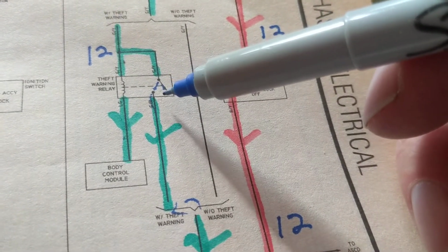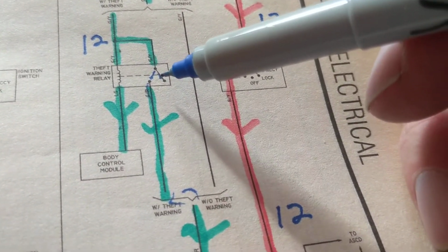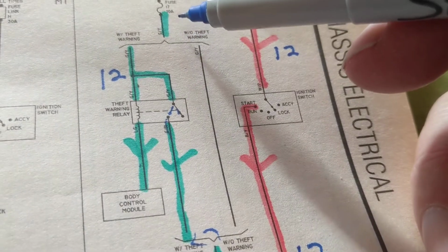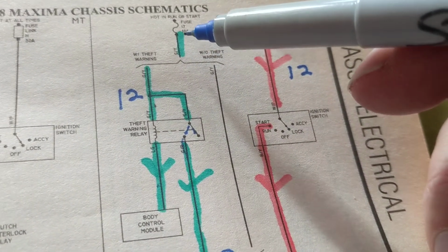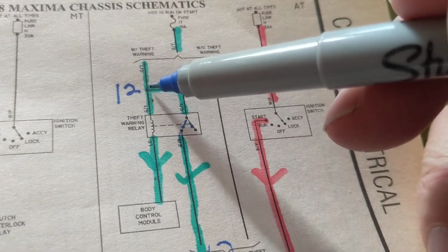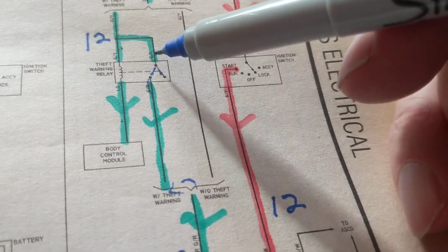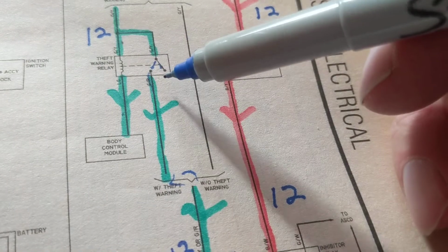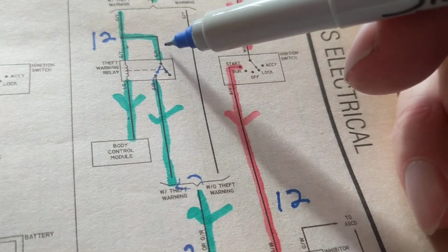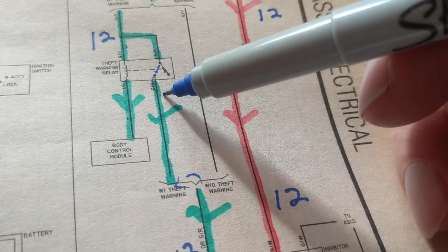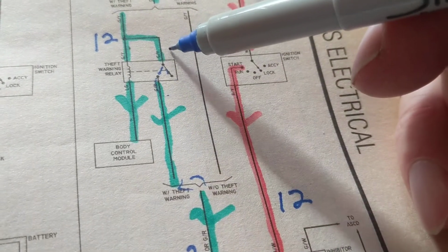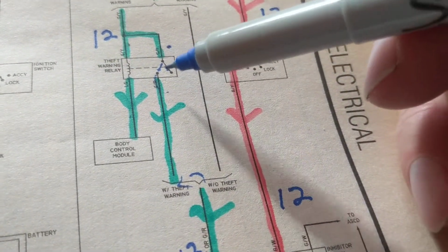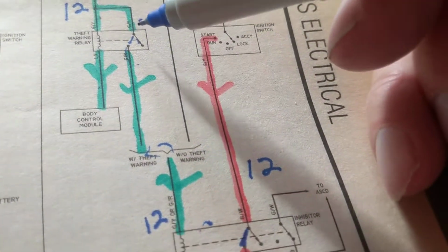We went through a switch. Is there a voltage drop through a switch? No. Therefore, we do not lose any voltage. 12 here, 12 here, 12 here. 12 comes in, 12 goes out. Why? No voltage loss. If this will be 10, this will be 10. This will be 9 volts, this will be 9 volts. No voltage drop across it.